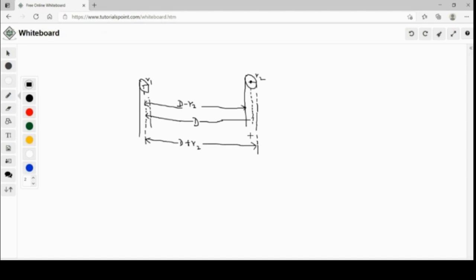Now, in the beginning, let us consider only the flux linkages of the circuit caused by the current in conductor 1. The flux lines set up by the current flowing in conductor 1 at a distance equal to or greater than D plus R2 from the center of conductor 1 do not link the circuit, and hence are not responsible for inducing any voltage in the circuit.